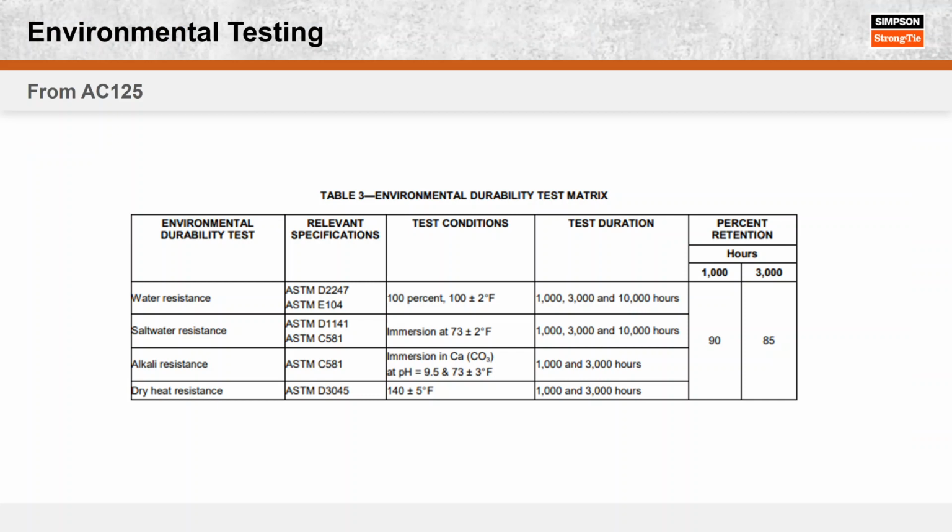So say you create 2 panels of FRP, and one of them you test as a control. You make the FRP panel and then you do a tension test on it. It's a control specimen. Then you have experimental specimens, your test specimens, and you expose them to different things. One of them is just regular water. Another one is water with salt in it.